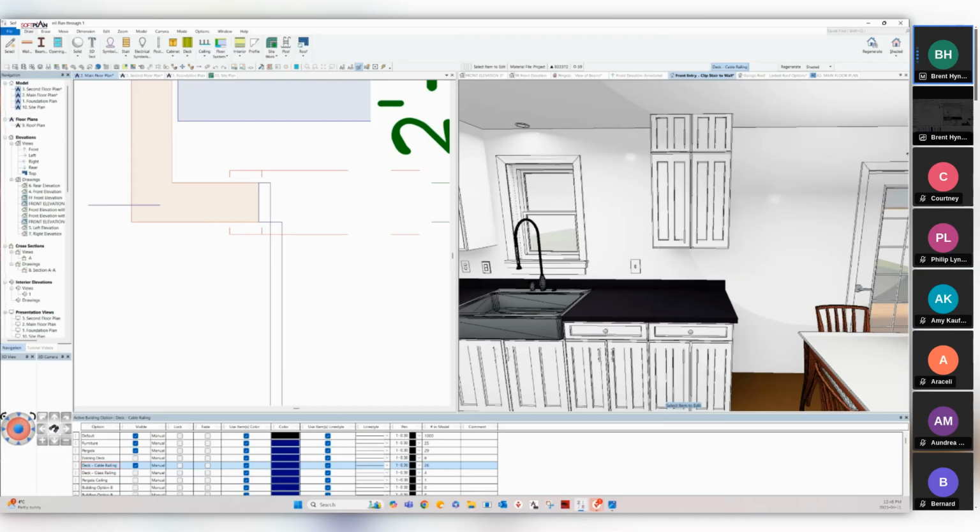So here again, right click on the cabinet where you want to place a wall cabinet above. So add wall cabinet. And then on that cabinet, you can stack on cabinet. We're just going to the ceiling with this one. It just gives you an idea of how you can do both of those things with that simple tool. Remembering that if you edit the cabinet, you also have the ability to add to the left or add to the right, as well as add your fill cabinets in.